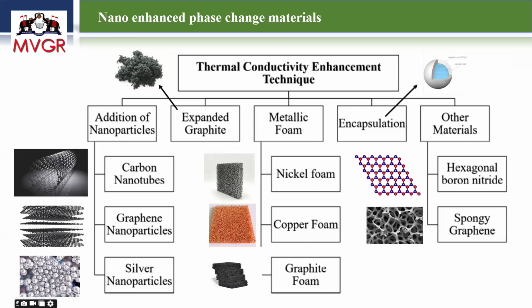If you put the sponge in the water, what will happen? The water will be stuck in the pores of the sponge. The same thing will happen here also. If you make this kind of material, even after heating, the liquid particles try to leak out, but because of these pores, they are stuck inside. So obviously we can arrest the leakage issue, and we can improve the thermal conductivity.